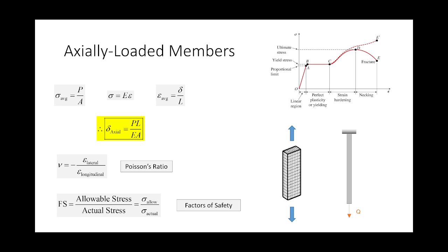Now, one of the things that we do to classify materials, and it is arguably the baseline, simplest, square one means of classifying material, is we take a piece of material and we yank on it and we apply load until it fails, okay? And by dividing out the effects of area and length, we can generate what's called a stress-strain curve. So this is a representation of the stress-strain curve of carbon steel. We tend to use carbon steel as a means of introducing the concepts of stress and strain and their relationships, because carbon steel is a material that you can sort of set your watch by in terms of its properties. They haven't changed in a very long time, and they're certainly not going to change anytime soon.